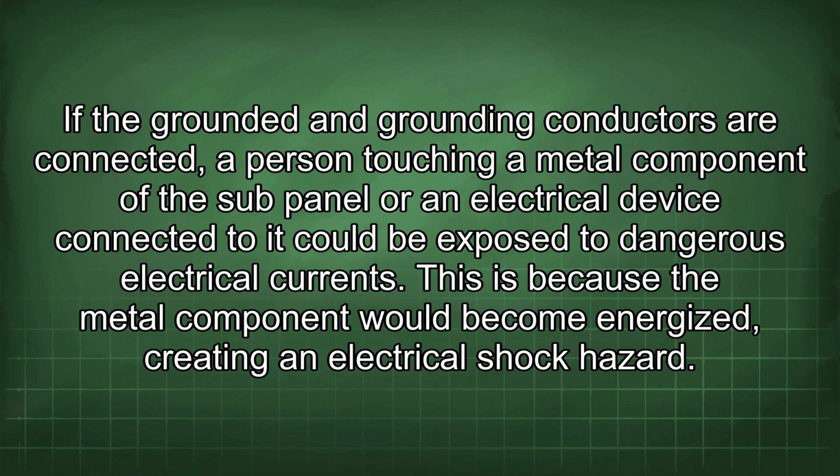If the grounded and grounding conductors are connected, a person touching a metal component of the subpanel or an electrical device connected to it could be exposed to dangerous electrical currents. This is because the metal component would become energized, creating an electrical shock hazard.